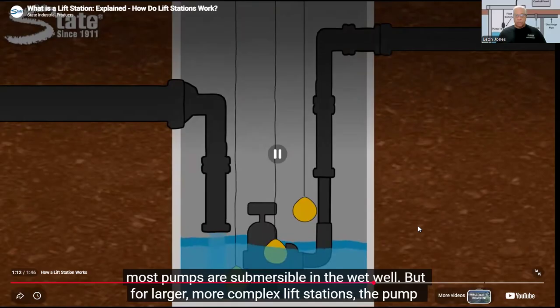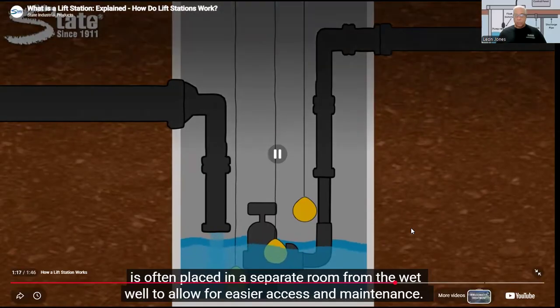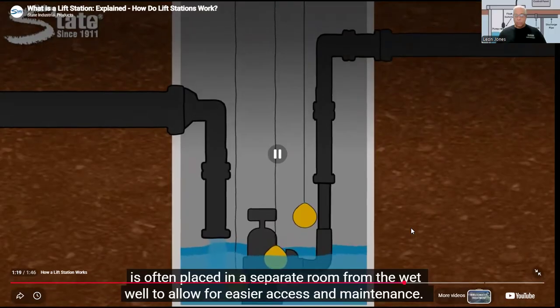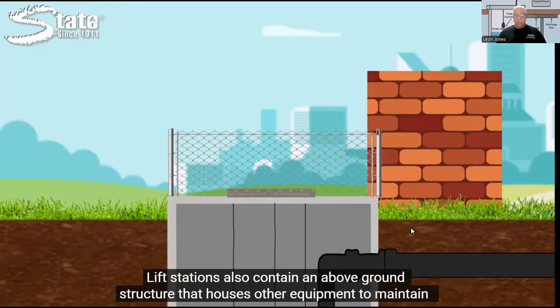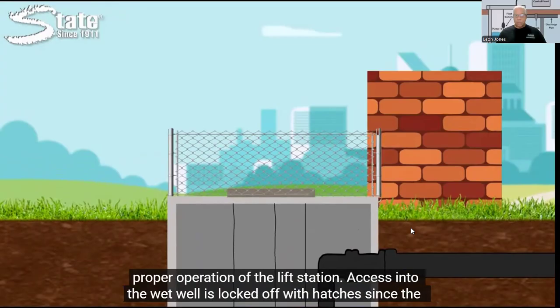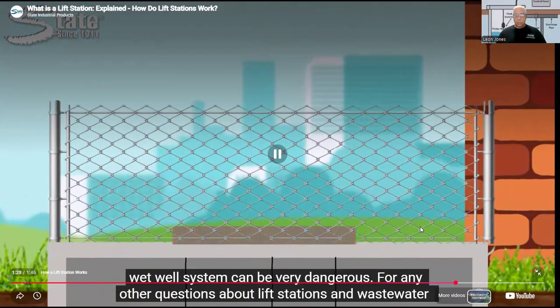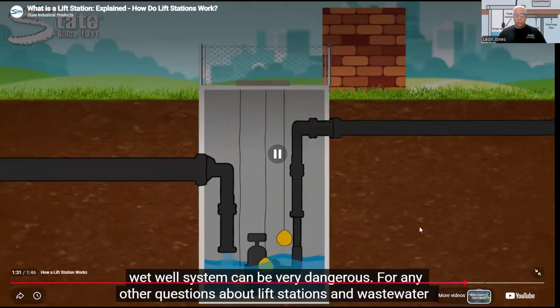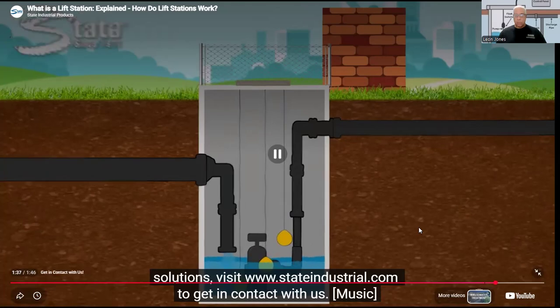For smaller sized lift stations, most pumps are submersible in the wet well, but for larger, more complex lift stations, the pump is often placed in a separate room from the wet well to allow for easier access and maintenance. Lift stations also contain an above-ground structure that houses other equipment to maintain proper operation of the lift station. Access into the wet well is locked off with hatches since the wet well system can be very dangerous. For any other questions about lift stations and wastewater solutions, visit www.stateindustrial.com to get in contact with us.